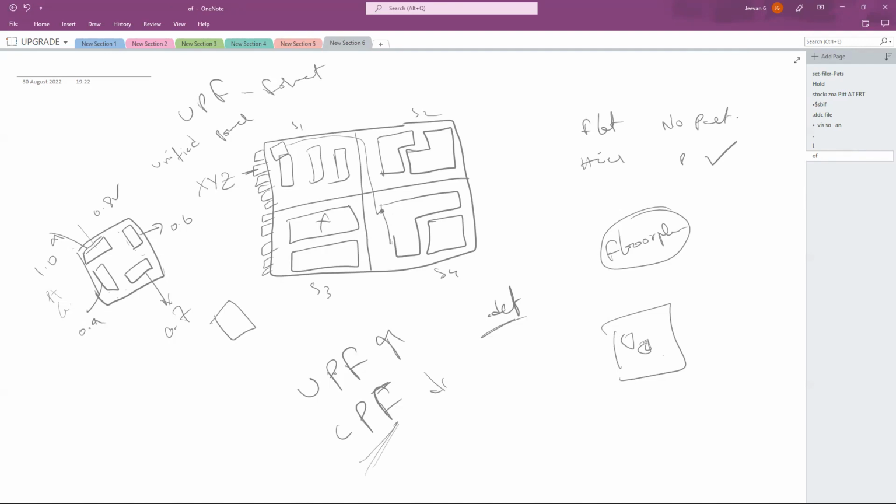Okay, cool. CPF is Common Power Format. If you don't have any voltage areas and the entire chip is working at a single voltage, then CPF, Common Power Format, applies. This is a very old version. Just for knowledge sharing, I'm telling this. UPF is the advanced and trending one, which is called Unified.